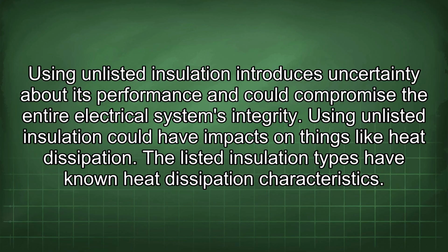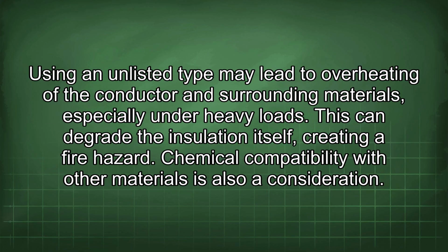Using unlisted insulation could have impacts on things like heat dissipation. The listed insulation types have known heat dissipation characteristics. Using an unlisted type may lead to overheating of the conductor and surrounding materials, especially under heavy loads. This can degrade the insulation itself, creating a fire hazard.